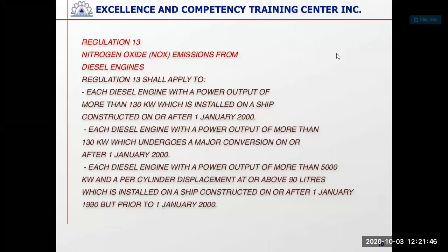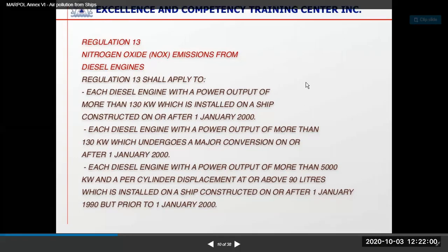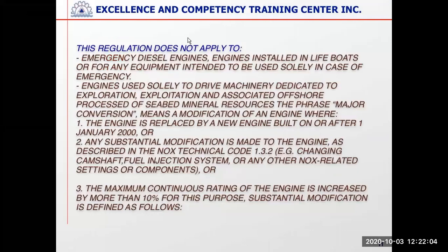And also if your engine is more than 5000 kilowatt power and displacement per cylinder is at or above 90 liters, which is installed on a ship after January 1990 and prior to January 2000. So these are the application requirements. Then which ships it does not apply to.